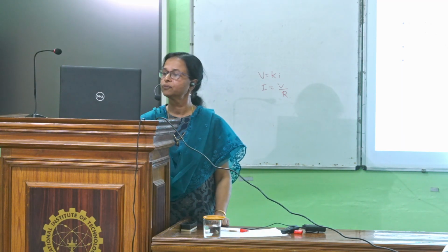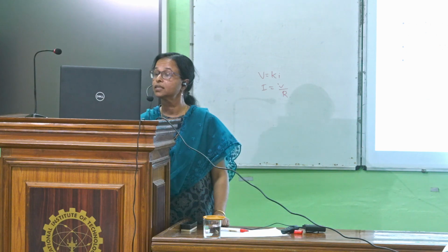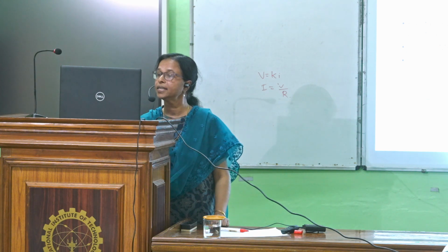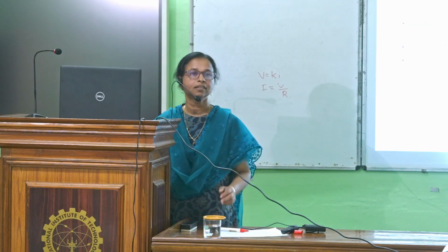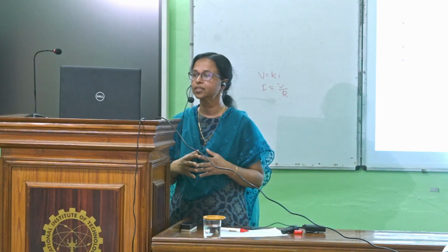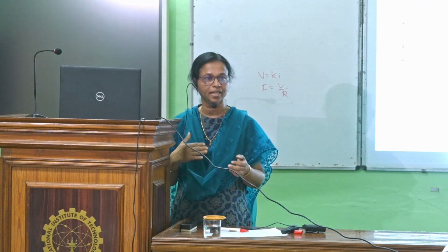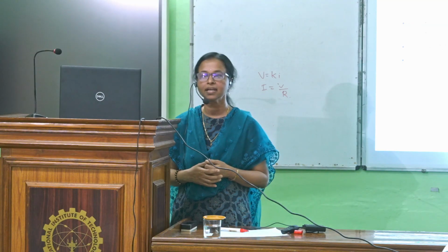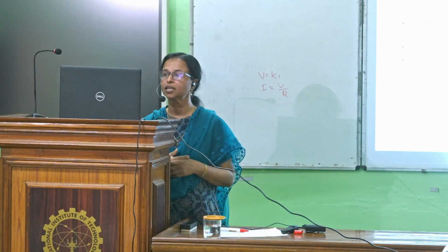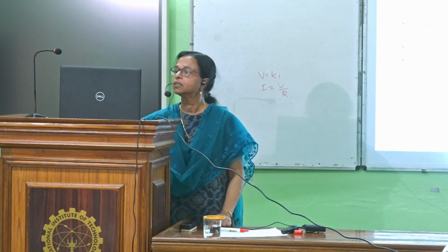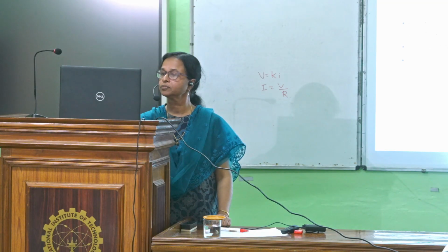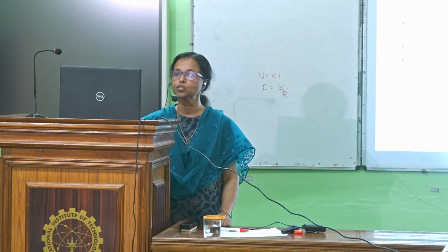What we found is, we used IMD gridded data, IMD station data, then TRMM data, then CHIRP data. In that, CHIRP was underestimating and TRMM was giving very good correlation with the station data. So again, we corrected the TRMM data based on the observed data and found the erosivity values. This is published in Water Resources Management.